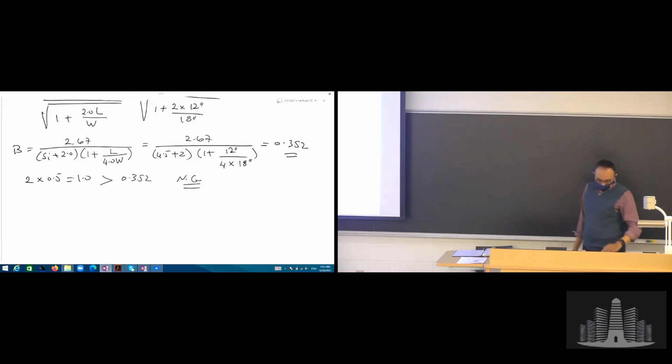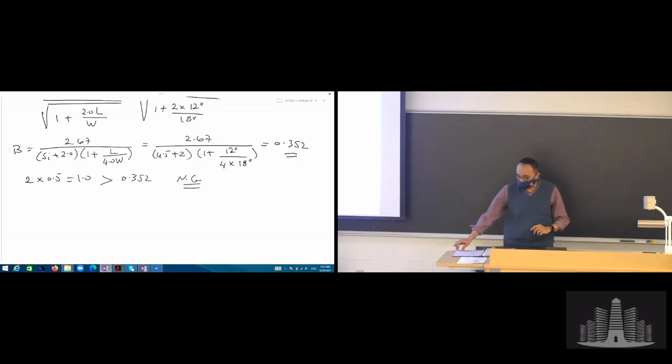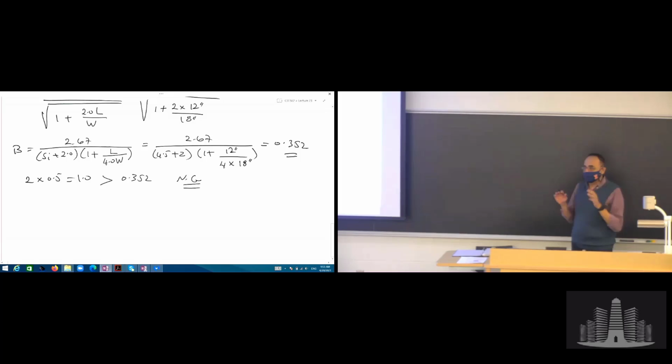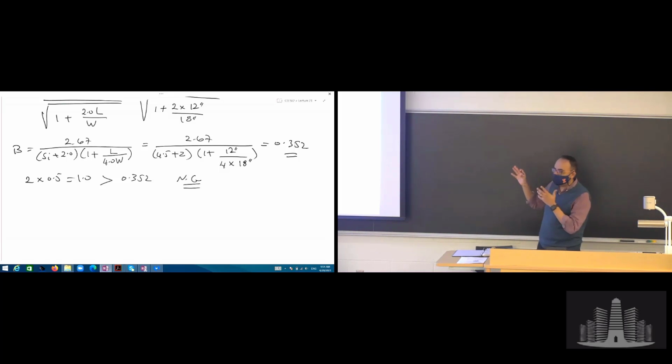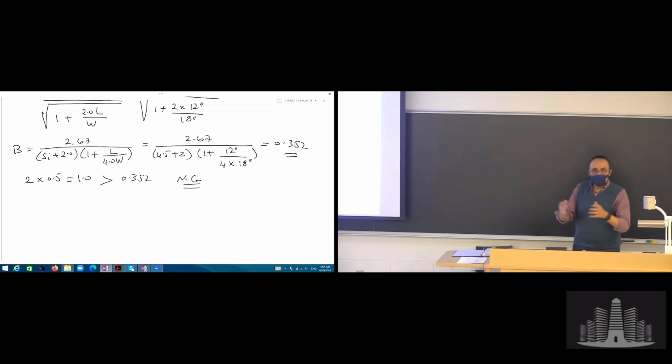That's not good. In this case, what should we do? Well, in this case, it doesn't mean totally that you are going to have to change the design. There's one more layer of check because everything we're doing now does not depend on the demand. So what if we have a very low demand on the bearing? Even if this check did not pass, because of the low demand, it might be okay to use it. But if this check did not pass and then you have high demand, meaning high compressive stress on the bearing, then maybe you ought to change the geometry, okay?